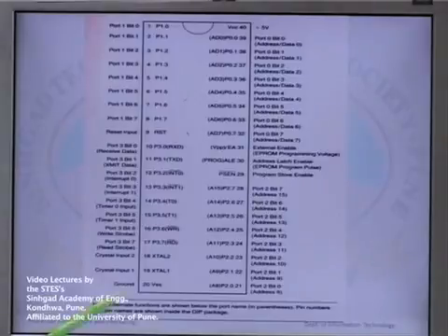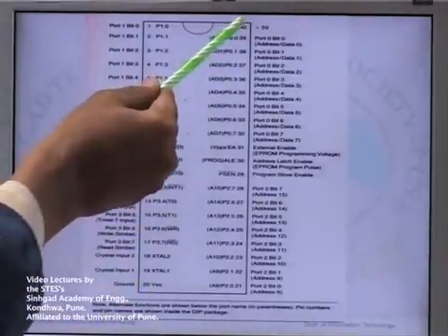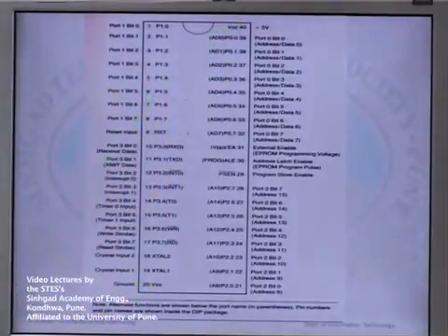Pin number 20 is ground. Similarly, pin number 40 is VCC. These are the supply connection pins for the IC 8051. So pin number 20 is to be connected to ground.